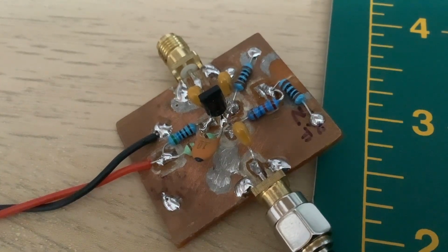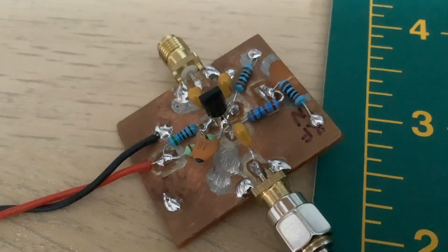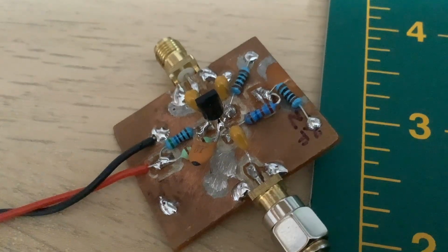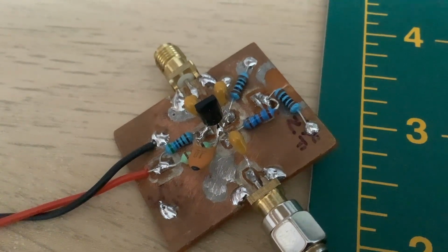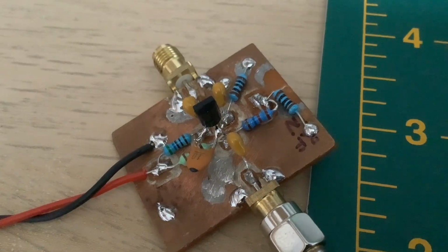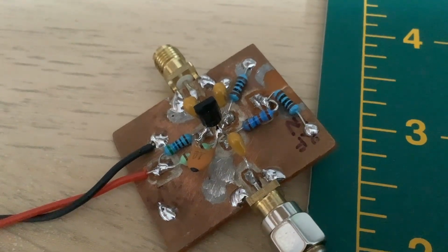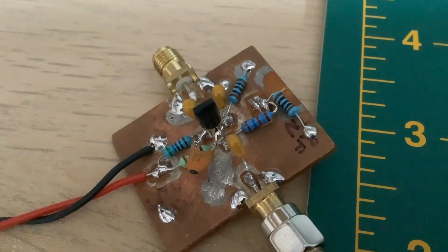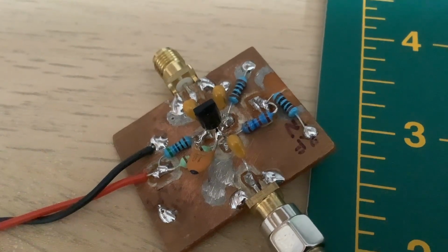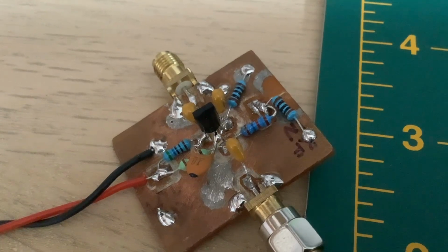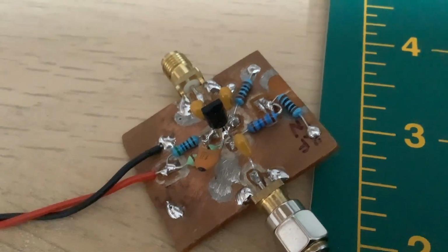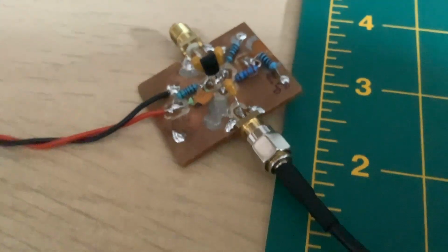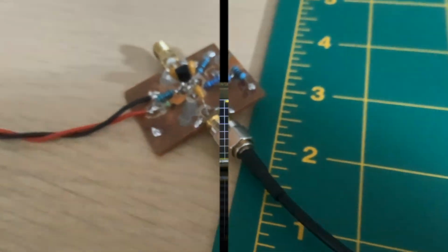Okay, so this is the amplifier now. It's switched on, powered up, open-ended on the output as usual. But just notice I've now soldered on this 10 picofarad cap, which hopefully you can just see, between the collector and the base, hopefully swamping out that intrinsic collector base capacitance, right? So that's what the circuit looks like. Let's go over to the nano VNA now, which it's connected to, and check out what we're reading.